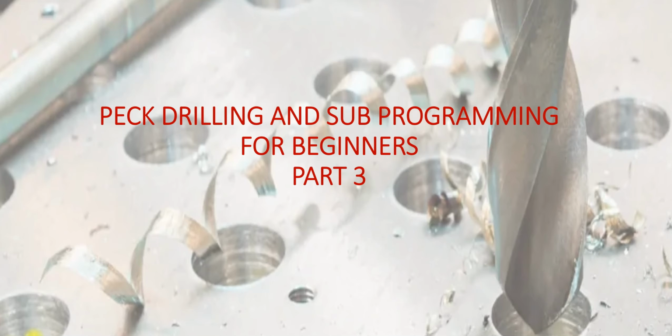So let's get started. First of all, we will talk about G83, which is a Peck drilling command. We will look at M98 and M99, which is subprogramming, and we will look at the O, which is a line number, and we will look at P and the L, which is program line and loops, which combine with the M98 command.